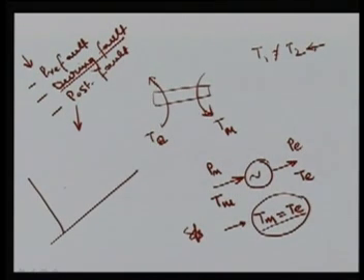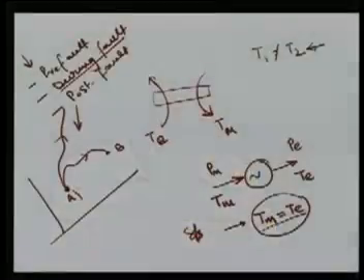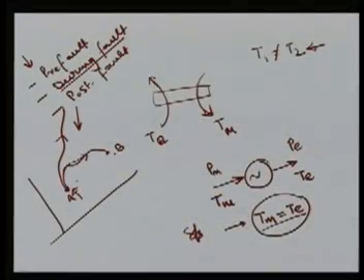multi-variable space, your pre-fault condition is point A and the post-fault condition is point B. Now, during the fault, whether your system comes to B with some trajectory, or goes somewhere else into an unstable condition. So the stability phenomenon depends on the pre-fault condition, the post-fault condition, and the system behavior during the fault. We try to analyze these trajectories. If you can get this trajectory in the time domain, then we can judge whether the system is stable or unstable.